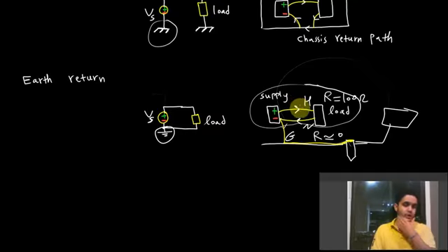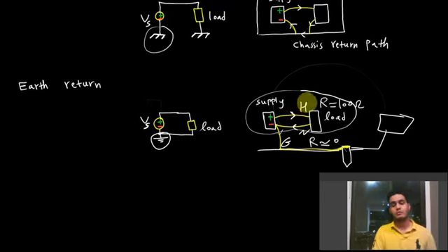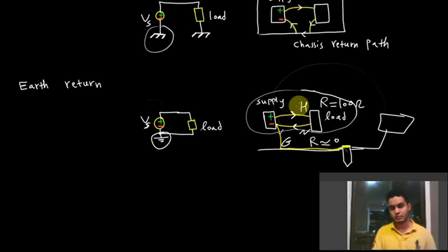Another application is, as you may know, ICs are very sensitive to electrostatic discharge. So it's very common to wear smocks at the workplace and to basically ground yourself at the feet and with your hands to a grounding mat on a table where you would be working. The reason for that is electrostatic discharge is thousands of volts, and it could easily destroy ICs, and you would never be able to detect it. Sometimes you can detect it. Sometimes you can see that a path is blown.